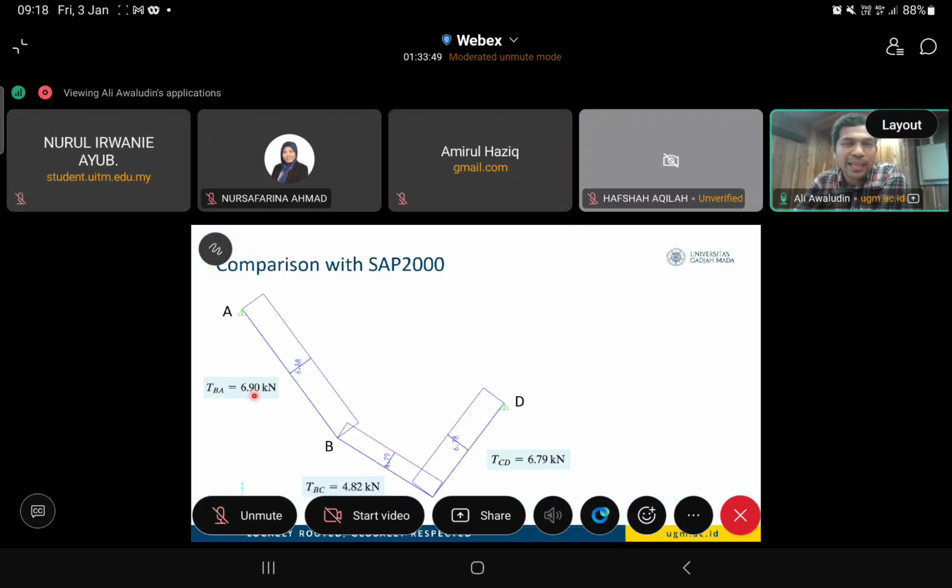Here, our calculation uses SAP 2000, which, maybe you are familiar with, is a commercial structural analysis program. Let's compare this. Using computer software depends on what kind of model, because in the software you must idealize the structures, the load application, the boundary conditions of the support, and all the points B and C. And you have to make the weight of the structures massless, because in our hand calculation we assume that the cable has no mass at all. Actually, in real application, it has mass itself. But sometimes, compared with the external load, the weight of the structure becomes small, so we can neglect it.